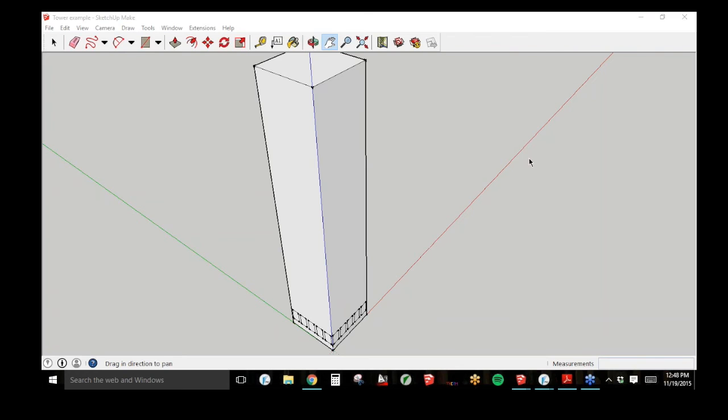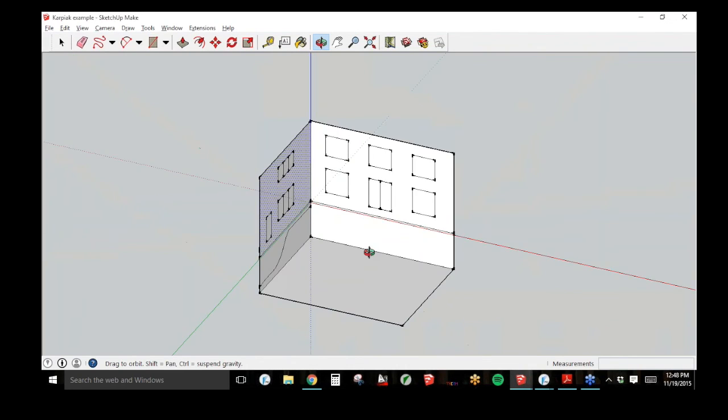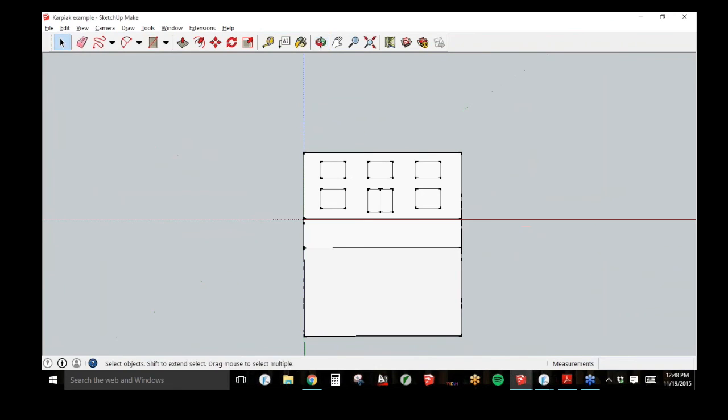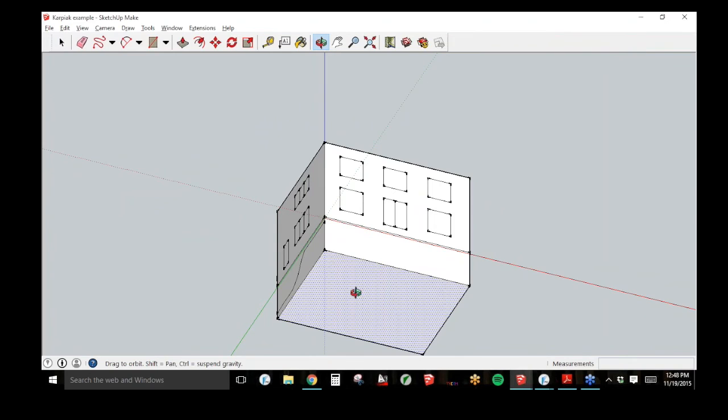Okay, the next question is for a slab on grade condition. Would the bottom plane, probably underfloor insulation, be assigned to ground? So yes. So that would be like, let's see, dock that. For this condition, the bottom here, this would be assigned to ground. So anything that was actually the ground condition would be assigned to ground, not outer air.